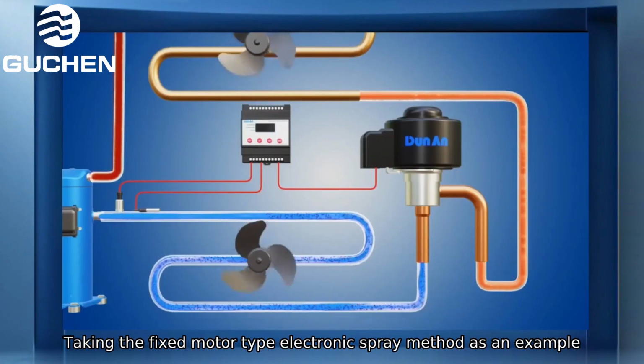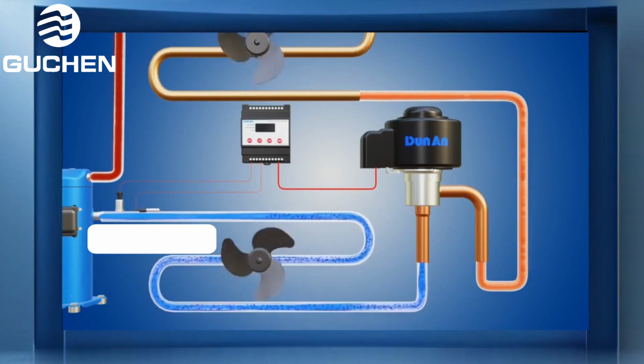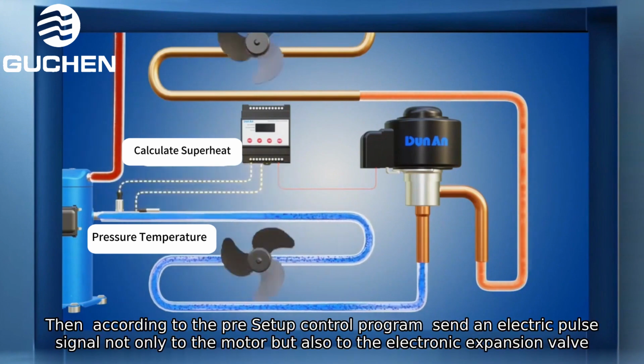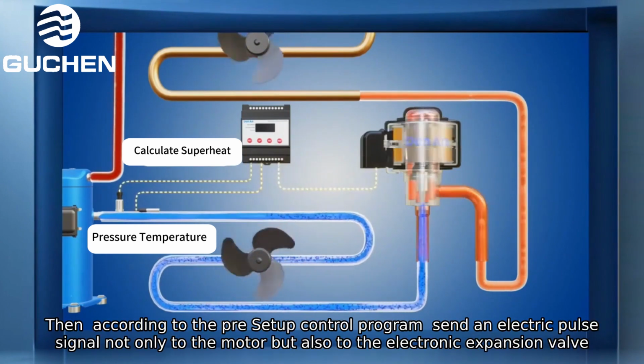Taking the stepper motor type electronic expansion valve as an example, the system first collects the pressure and temperature at the evaporator outlet, then converts and calculates the superheat at the evaporator exit. Then, according to the preset control program, it sends an electric pulse signal